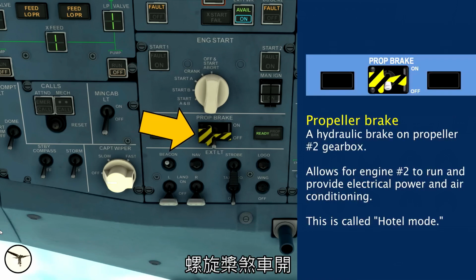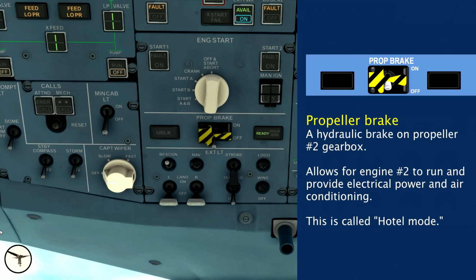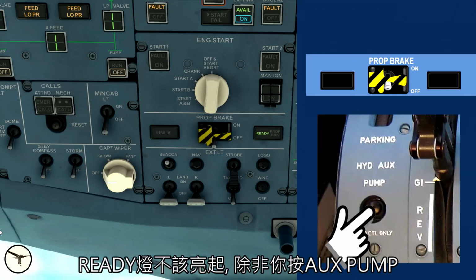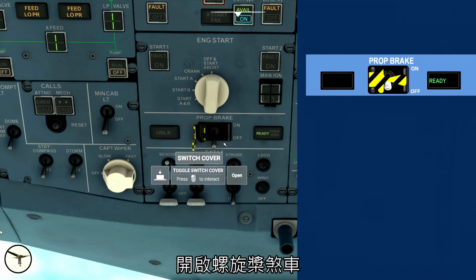The propeller brake should be on, and there is a bug with this version of the simulator model. The ready light should not be illuminated unless you have pushed the aux pump. You wait a few seconds, you get the ready light, and you can lift the cover and select the propeller brake on. Then we close the cover.